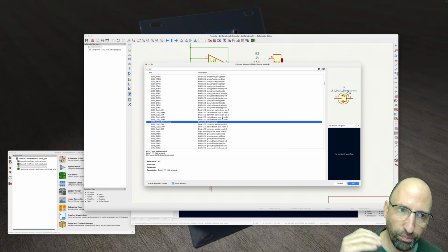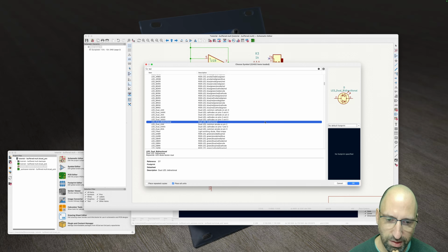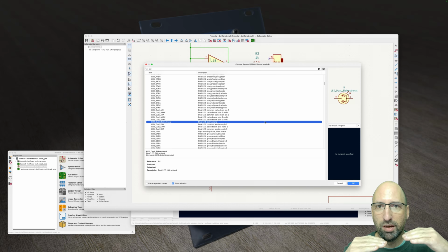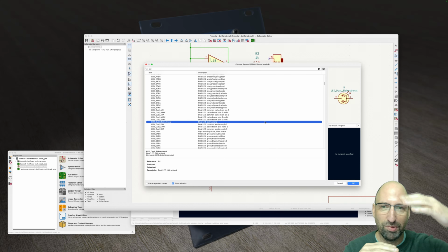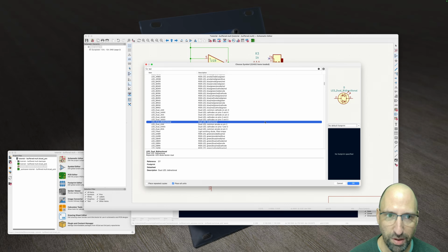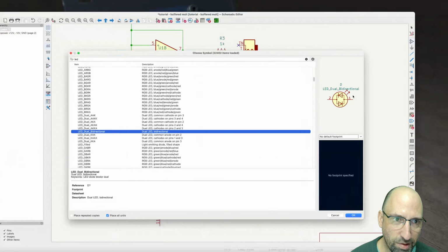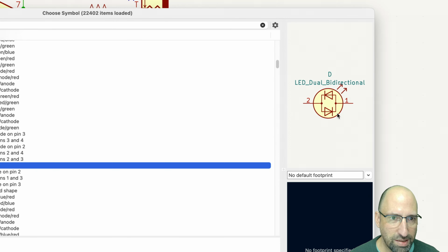So an LED is unipolar. It can only handle a 0 to positive voltage or a 0 to negative voltage, one or the other, but not both. So what we've got here, if you look at the symbol, is 2 LEDs. Imagine we put a positive voltage in here. It's going to be able to flow through this diode, but not through that one. So it will light this LED. If we send a negative signal in here, it's like a pulling. So it's going to pull through that LED and light that one.